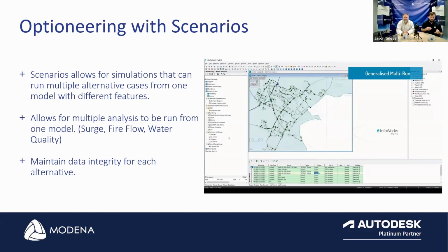How is a pump functioning? Are we actually working with different pipe diameters? Are we actually working with an entirely different network where in one situation, that node can be a fire hydrant, but in the next junction or the next model, that is then supposed to be an isolating valve? So with the control of one model, we can keep that efficiency of knowing that the information on the design data is true when we look at layouts, pipe sizing, and anything like that. But then the scenarios give us those if, but, and when situations so that we can have a lot better understanding of the network.